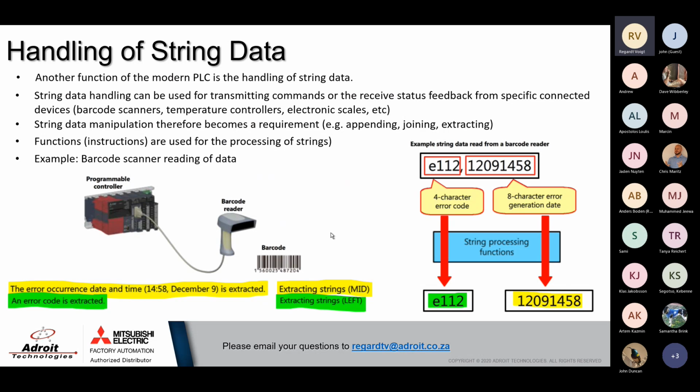Traditionally, and off the topic here, barcode scanners are most effectively applied, configured and interfaced with a MELSEC iQ-F FX5U PLC, or any MELSEC PLC, in conjunction with a GOT, because of the GOT's inherent functionality for the handling of barcode scanners and their data.